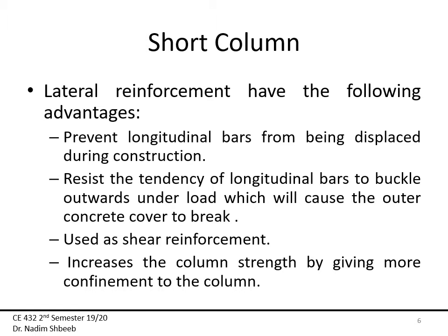So why do we have lateral reinforcement? Well, first of all, from a constructional point of view, it prevents the longitudinal bars from being displaced during construction. Usually, it is very hard to deal with longitudinal reinforcement, especially in columns, due to their length. So it's better if they are caged together. If I put a tie on, let's say 4 or 5, depending on my design, I usually call that a cage, and that's much easier to handle during construction and much easier to put in place than if I would do it individually.